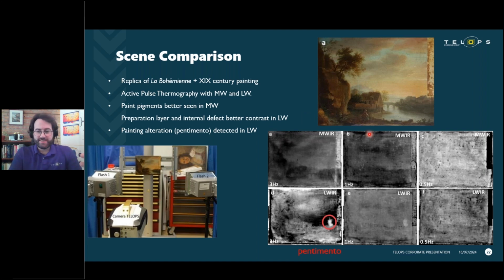Not only that, but you can see stains in textiles, you can see other marks and the preparation layers on the textile, comparing the midwave and the long wave images on this target. So it's really interesting. That combination of different spectral bands offers a way to do non-destructive testing to compare the material properties and material status, basically the state of the different layers in this case.